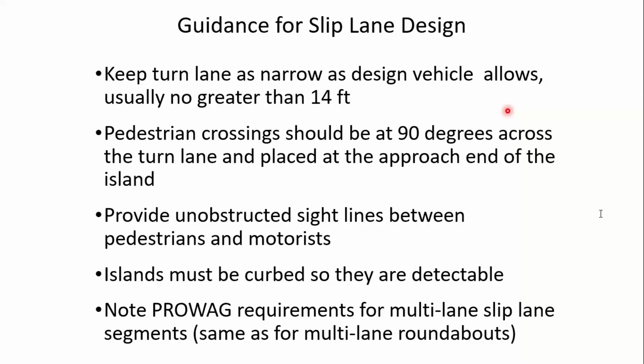And we may talk about a treatment next week, but if the roadway is uncurbed and people are walking, if I'm understanding you correctly, on a sidewalk that is at the same elevation as the street, that makes it difficult for the visually impaired to navigate because they don't have their shoreline or edge on the curb side of the sidewalk.